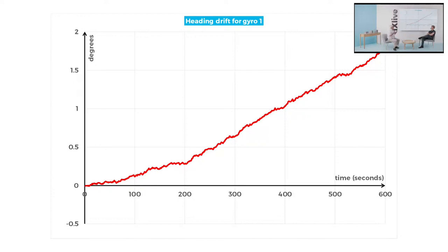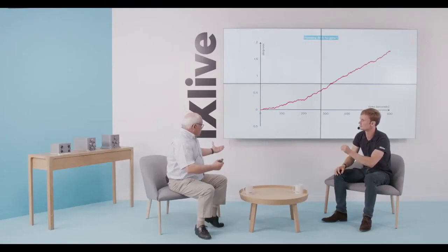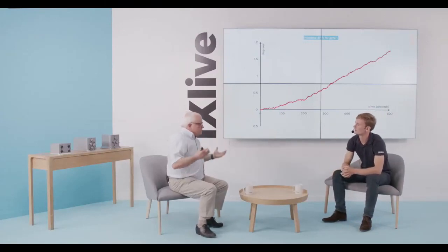So to try to estimate the bias of the sensor while the GNSS is available. And then I imagined no more GPS, and then I integrated the measurements from the gyro. So we can assume that the beginning bias of this curve is really good. You've estimated? Yes, or it has been estimated in the best way possible.